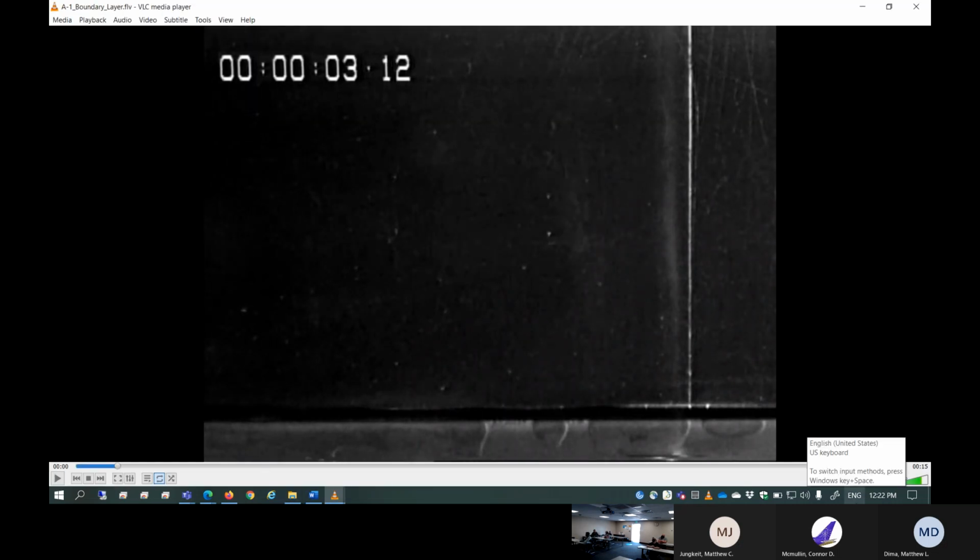Okay, so this is a boundary layer flow visualization. This is the water coming in from right to left. This is the solid surface. Water is incoming. Velocity on the solid surface is 0. As you move away from the solid surface, velocity gradually changes and hits the edge velocity. So you can sort of tell the boundary layer thickness of this case. This is a laminar boundary layer.